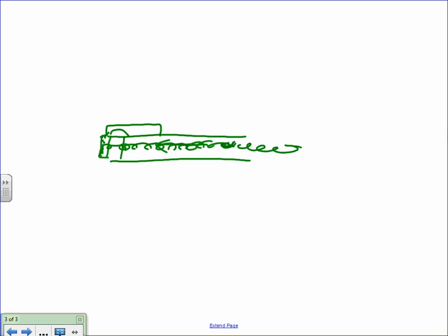Now this return air isn't being distributed throughout the building, or wherever you return. It might come back into the mechanical room. So basically the smoke won't be blown throughout the entire building. It'll shut that air handler down, and that alleviates that.